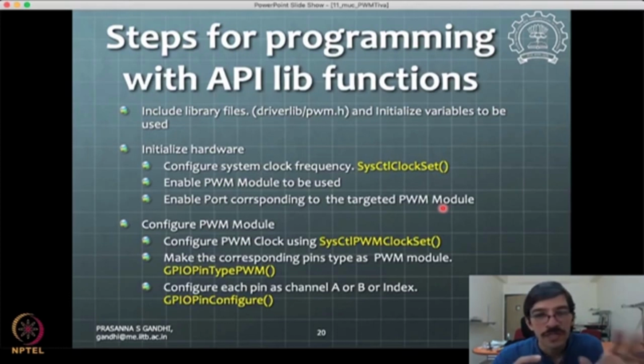So the motor driver data sheet also will be uploaded on the thing. So these are different things. The important part here is that you need to configure this PWM module, and there are many different aspects of configuring. So configuring the clock: we saw that the block diagram needs a clock, so this is done by this command.